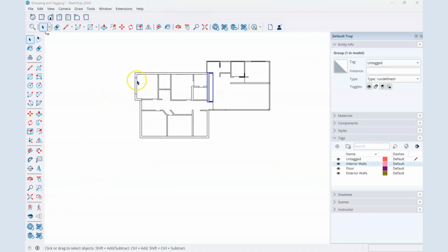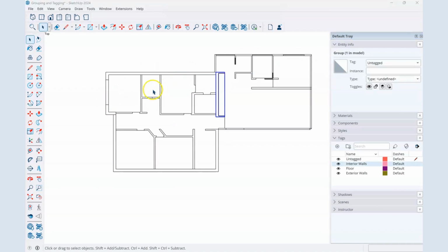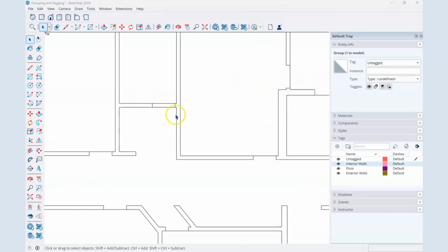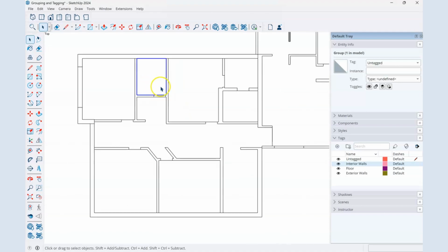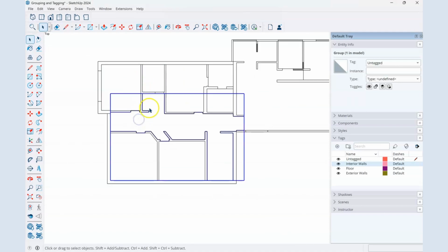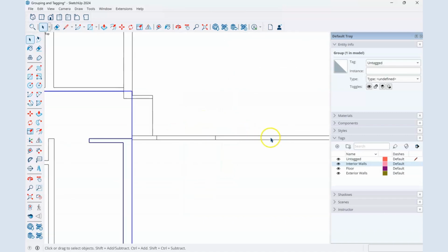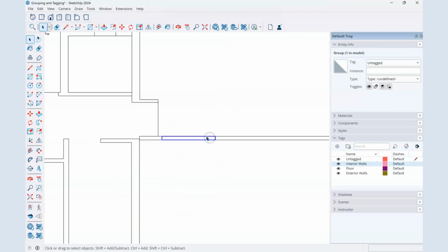Okay, so I've worked my way around and I did that. I found myself zooming in a lot just to get some of these aspects correct. I also found using the G for group shortcut quite helpful. Now in theory, if I click on any bit of geometry, I should be getting what you're seeing now and not just seeing the blue face appearing or a single line or edge appearing. Just looking at it, it looks like I have grouped everything.